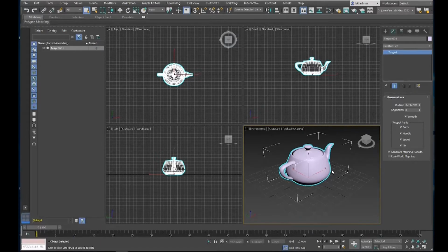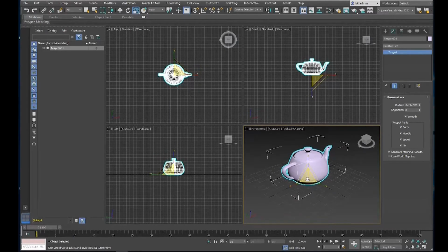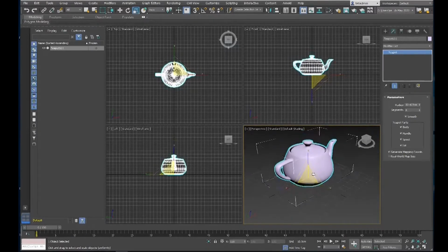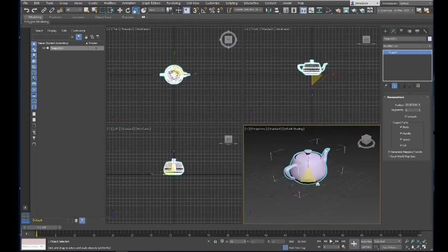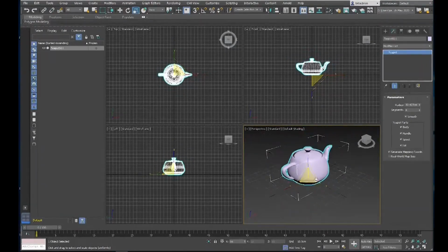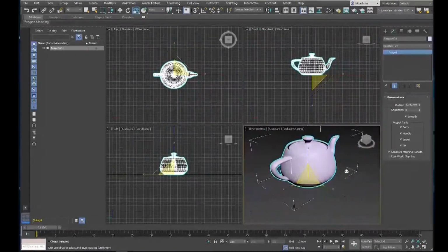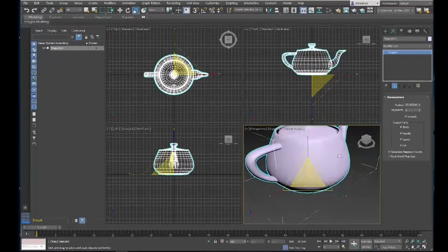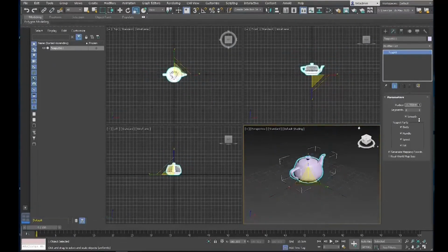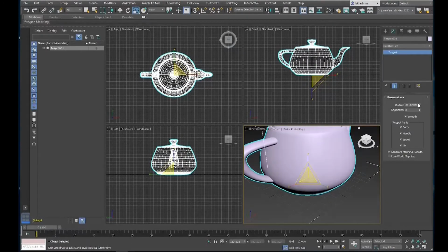But here comes kind of an issue. If I'm switching to scale, select and scale, here's the button for select and scale. The hotkeys are like Robert, so pressing R as Robert. I don't want to cycle through this, okay? And if I'm using the scale, this is what happens. Please look at the screen. When I'm scaling up and down the teapot, the display size changes, but the radius here does not. And the funny thing, you can scale it up, and this radius is still live. It is just not true anymore.